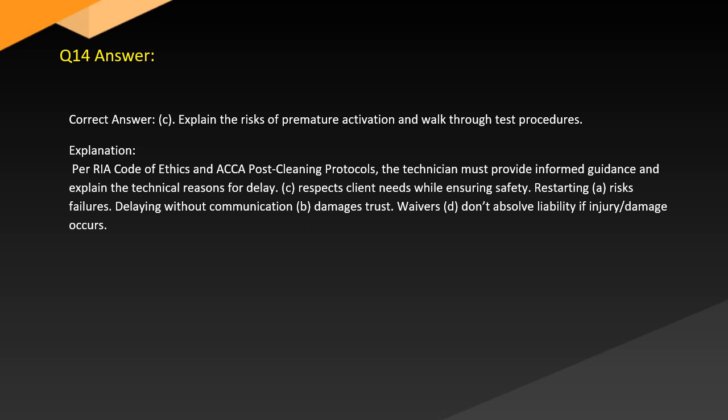Answer. Correct answer: C. Explain the risks of premature activation and walk through test procedures. Explanation. Per the NADCA Code of Ethics and the post-cleaning protocols, the technician must provide informed guidance and explain the technical reasons for delay. C respects client needs while ensuring safety. Restarting, A, risks failures. Delaying without communication, B, damages trust. Waivers, D, don't absolve liability if injury or damage occurs.